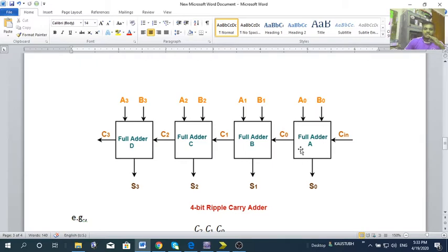Otherwise, if it is a half adder, you cannot use the complete 4-bit parallel adder as a module for a 16-bit parallel adder. Hope you understood. So for modular design, we always prefer the first one also to be a full adder instead of a half adder. But if you explicitly design only a 4-bit parallel adder, then the first one can be a half adder as well.